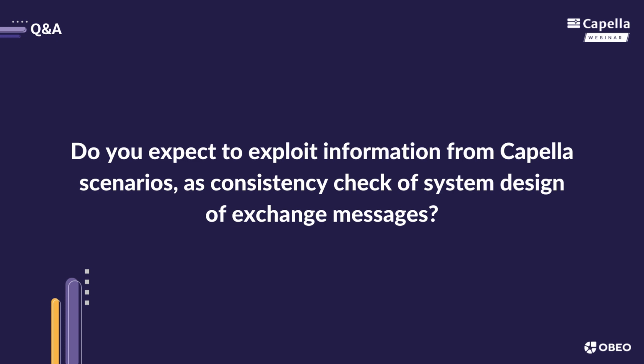Here I use composition. I think it's not a problem. I use composition because in ModelCenter MBSE, what I want to see at the end of the day is one system, and this system is composed of different subsystems with different parts and multiplicity involved. So basically, it's to provide a context. When I connect my simulation models to Capella, I want to be able to say, look, I'm actually connecting to the wheels that are part of a vehicle.